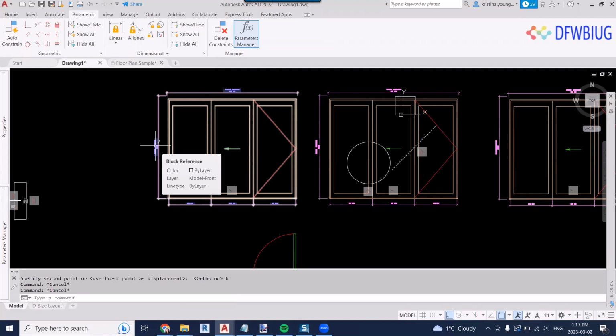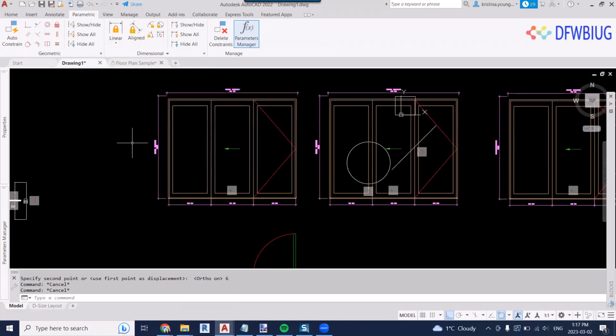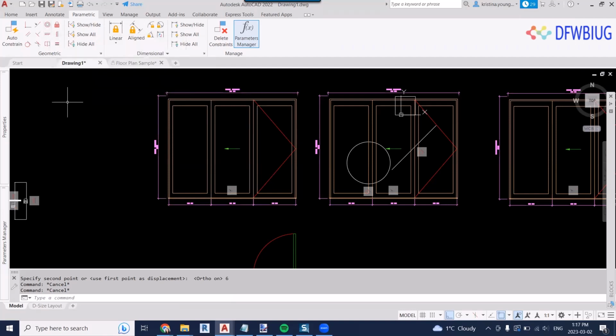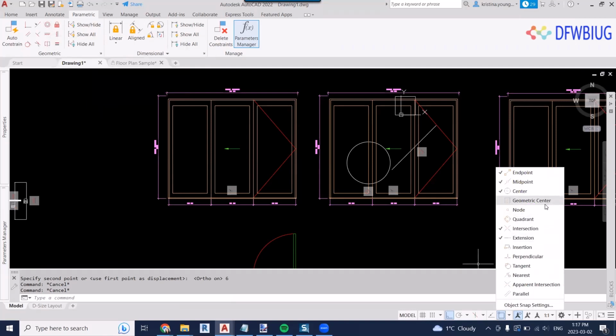We had a few members saying, don't forget to use the geometric center when you're doing rectangles and squares on your object snaps. Yeah, when you go to object snaps, there is a geometric center. So we'll just bring that up. It's for rectangles and squares. It's not new, but I always keep forgetting about it. I can't remember when it got introduced. It was added somewhere in one of the 20 versions. So it wasn't 18 or 19, I don't think. It wasn't recent.